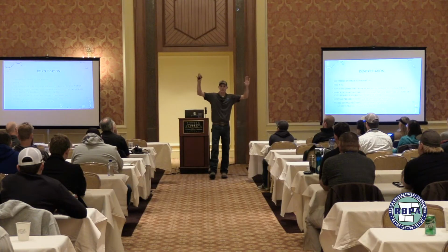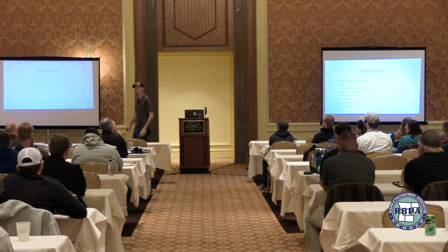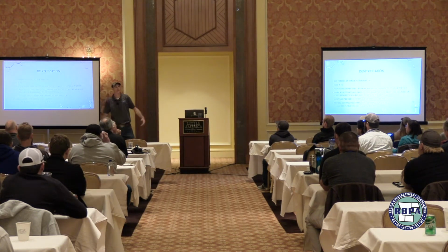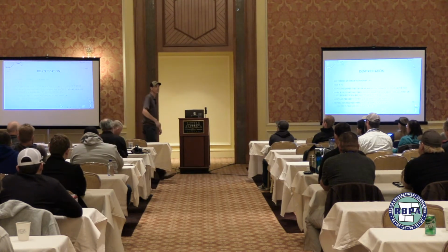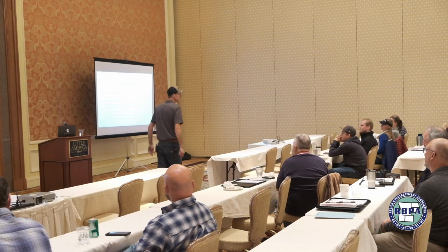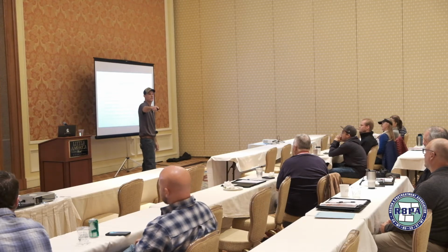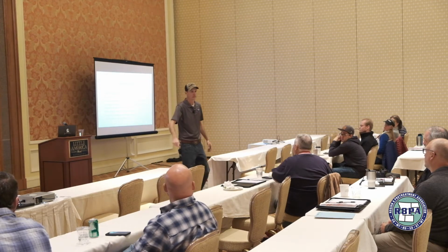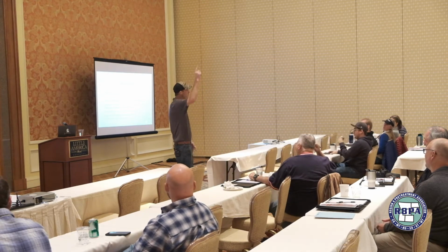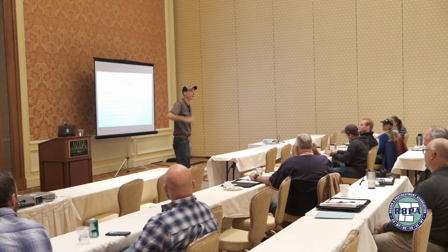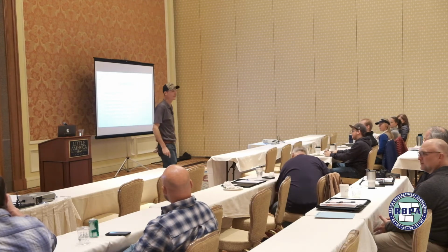Now, who's done a local limits evaluation for your plant? Has everybody noticed that biosolids portion? You've got to know what your biosolids are to develop your local limits. Now, who's in charge of making sure your biosolids are in good shape? Is it you guys? Is it the pre-treatment folks? Biosolids coordinator? Well, forget that guy. The operators, thank you, whoever said that. Your operators are the ones that determine what your biosolids concentration is based on the process that they do.